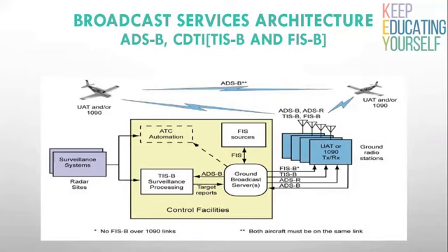While ADS-B increases safety, TIS-B significantly enhances pilot situational awareness for additional safety benefits. With traffic displayed in the cockpit, pilots and air traffic controllers are able to communicate with shared awareness of conflicting aircraft traffic. With TIS-B, a pilot will not only see ADS-B air-to-air traffic but also the radar targets sent from ground ATC radar position, resulting in a more complete picture of traffic around the aircraft.